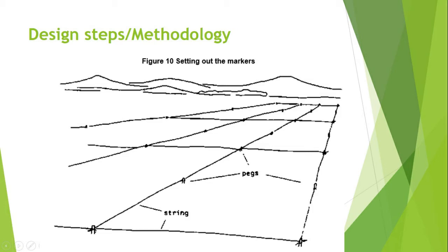On flatland, basins may be square or rectangular in shape. On sloping or undulating land, basins may be irregular in shape and terracing required. Terraces are set up so that the bunds are located along contour lines. The differences in elevation within each basin should not be excessive so that the amount of earth movement required to obtain a level land surface is small.